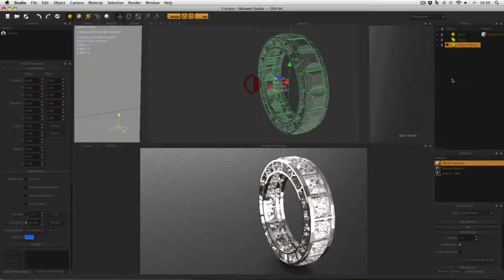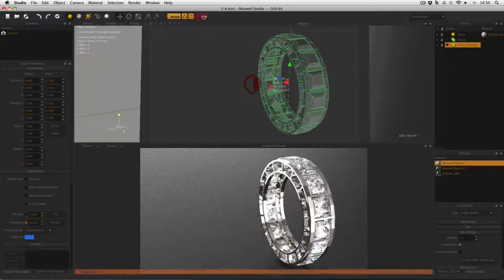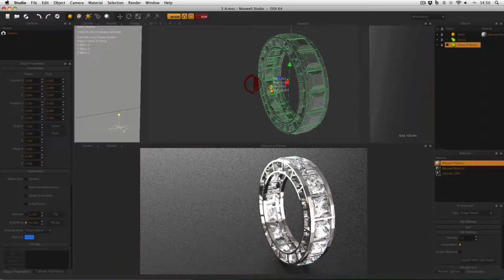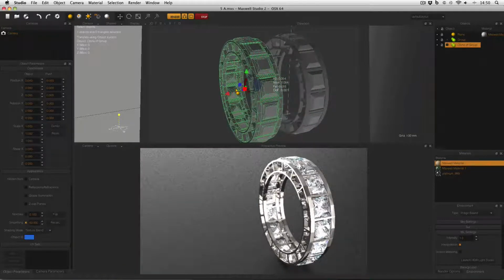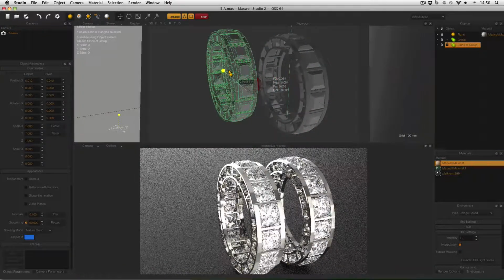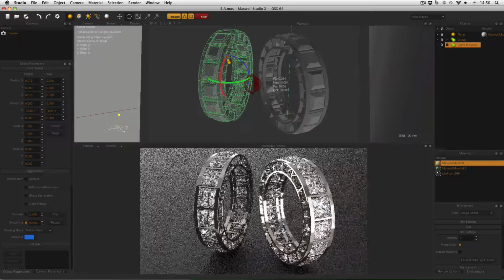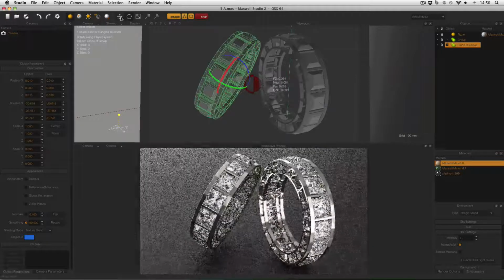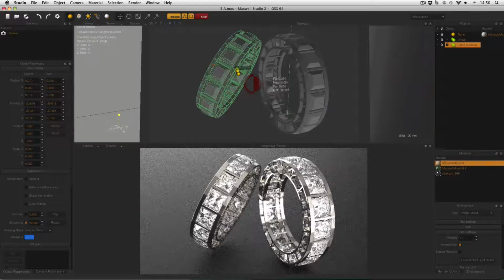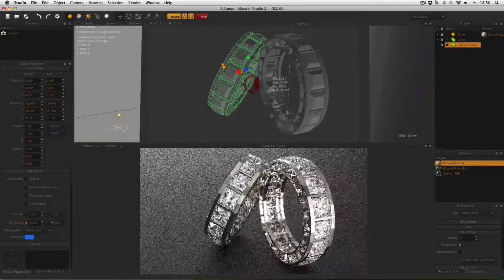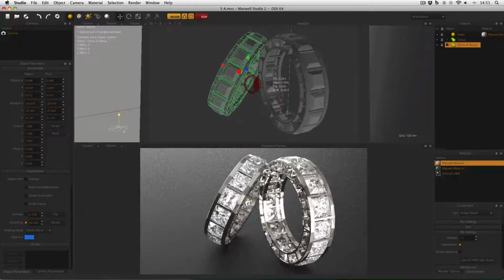So then I'm just going to close that group and then activate my fire window so that it updates automatically. Then what I'm just going to do is use the move tools to move this group out and move it to approximately where I want it to. Then use the rotate tool, rotate it around a bit, and again move it to approximately where it should be. And although that might look good-ish, or maybe good enough, what I need to do is go to my perspective view to make sure that I'm not getting a lot of intersections at these edges, where this new ring is touching the old ring and the floor.